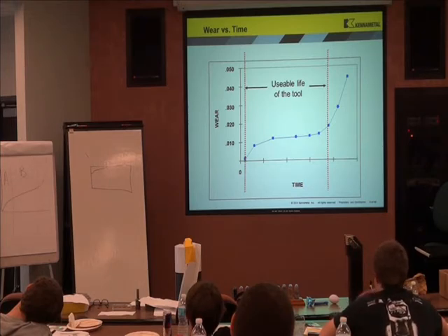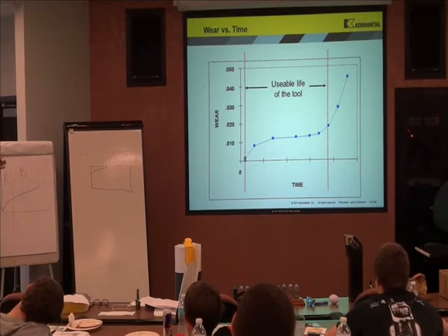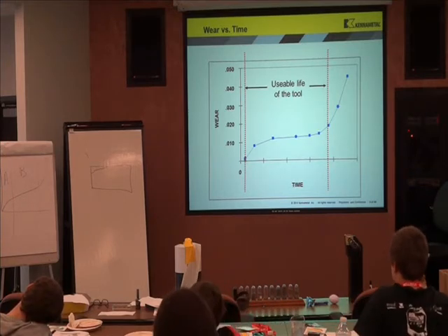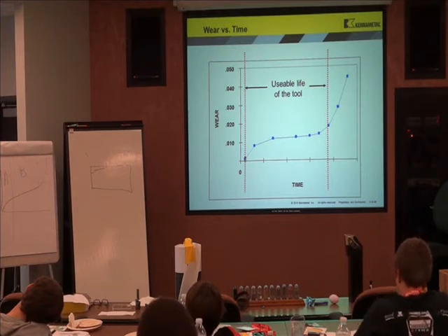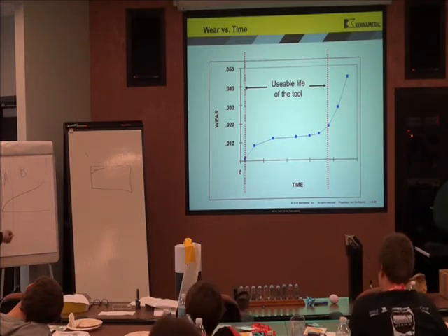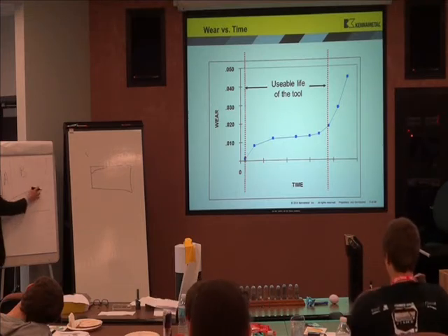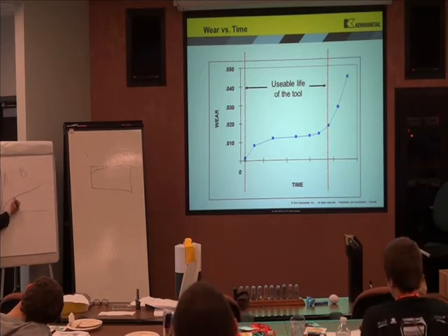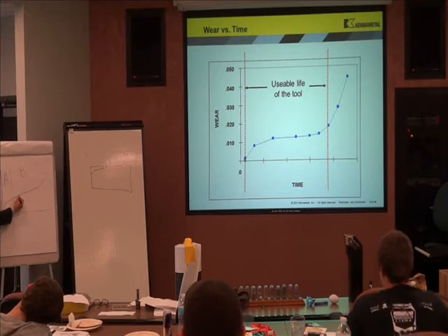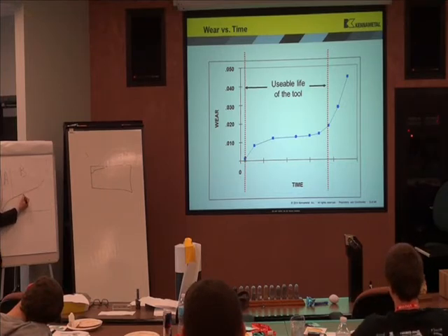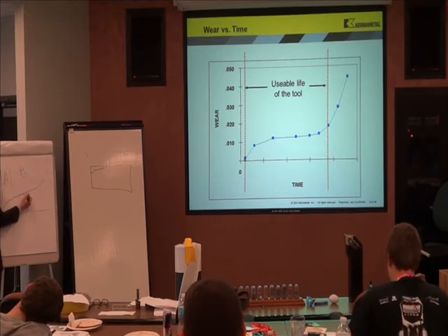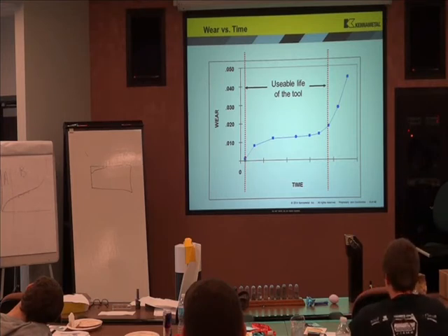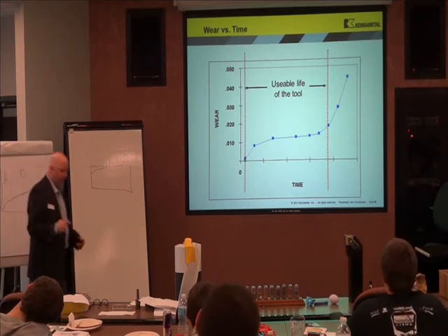I mean, you have steps in your house or leading up to your house. You know with steps you have what they call a rise over run. Every step has to be the same height versus width. The state codes are really picky about that. That's the same thing that happens in this zone. What I mean is for every so many minutes of cut, I get the same amount of growth of wear. It's a constant wear zone.